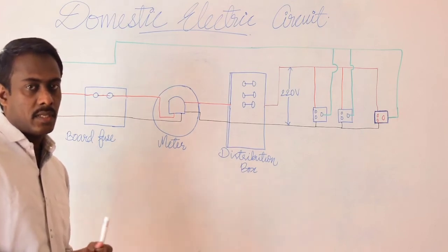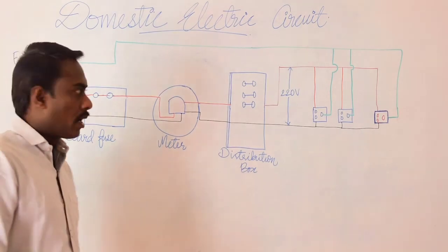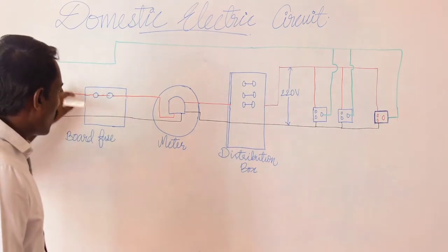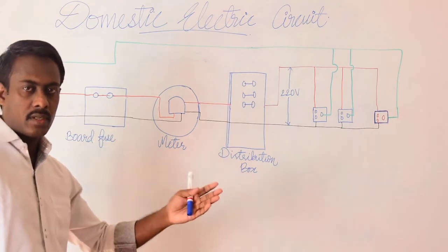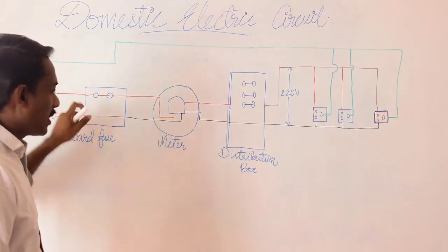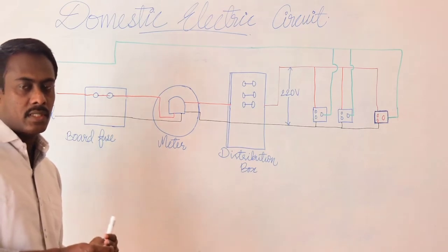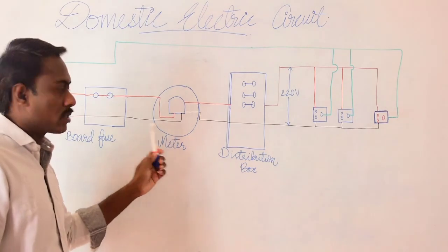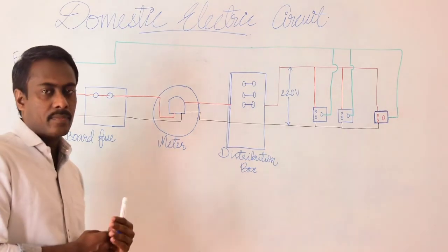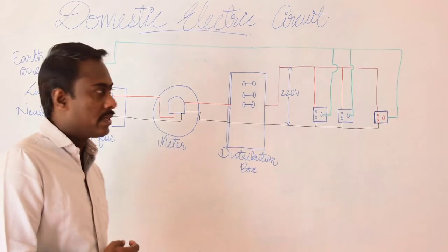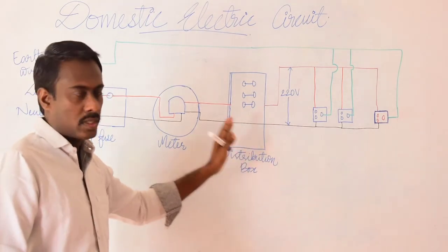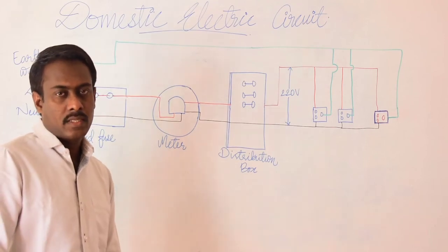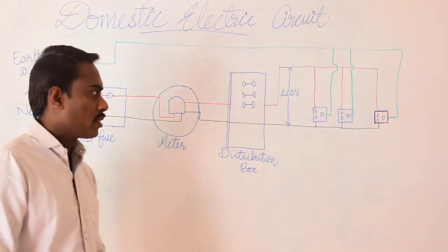Again, in another case, if the live wire and neutral wire come in direct contact with each other, it leads to overloading. This sometimes happens due to wear and tear, when the insulation of these wires may be spoiled or destroyed. When these wires come in direct contact, a high increase of current will take place in the circuit, causing short circuiting and may lead to a fire.